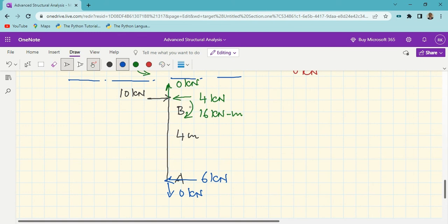And the bending moment, that is very much interesting. The acting moment, this 16 kilonewton meter, is a clockwise moment. It is acting like this. So this 16 clockwise, I am just showing this 16 kilonewton meter moment acting at A. I am writing the description: acting moments at A, and I know I should apply the equal and opposite moment for the reaction. So 16 kilonewton meter, it's a moment, it will not be multiplied with distance, so 16 as it is.